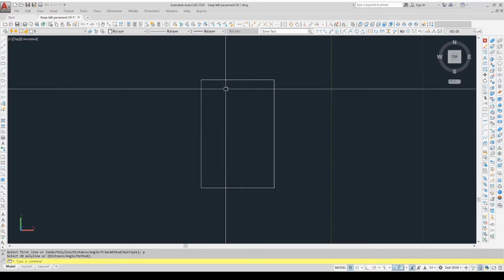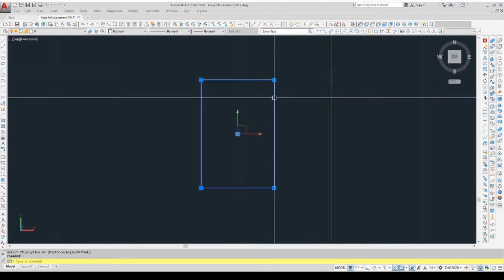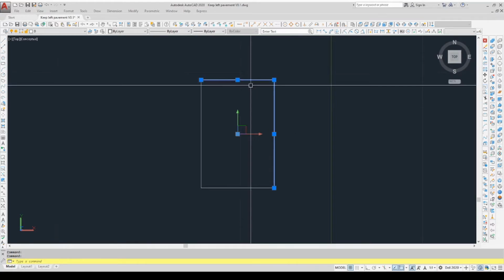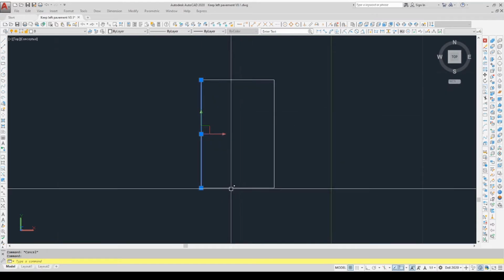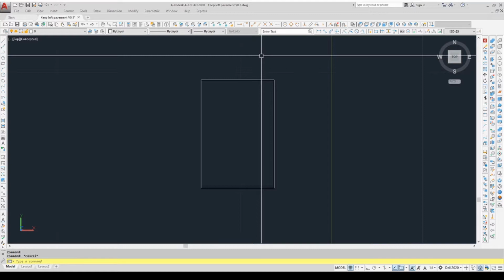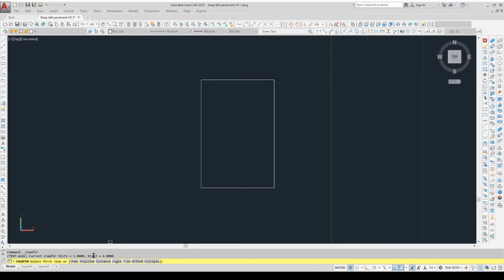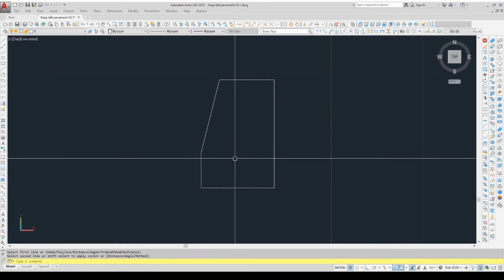So the best way to do this is to break it. Well, again, there's more than one way. Nothing's ever simple in CAD. So I could grab that, press explode. So it's now not a continuous rectangle that CAD understands is a rectangle. It's just 4 lines that I can select individually. And now when I come to do the chamfer, the distance is remembered. So we'll presume that's the 1 inch and that's the 4. Yep, it's showing me that it is. And hey presto, it's done it.